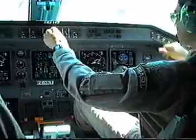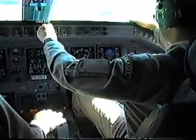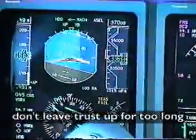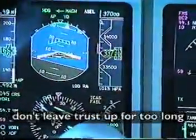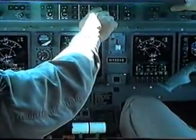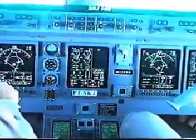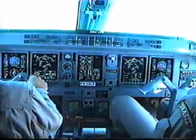Similarly, if an excursion to high thrust has been necessary to cope with a high loss of speed, don't leave thrust up for too long, or the airplane will go too fast again. Reduce thrust fairly soon, and you will fly on the target stabilized speed again conveniently. More will be said later when we discuss the aerodynamic matter involving turboprops and turbofans.